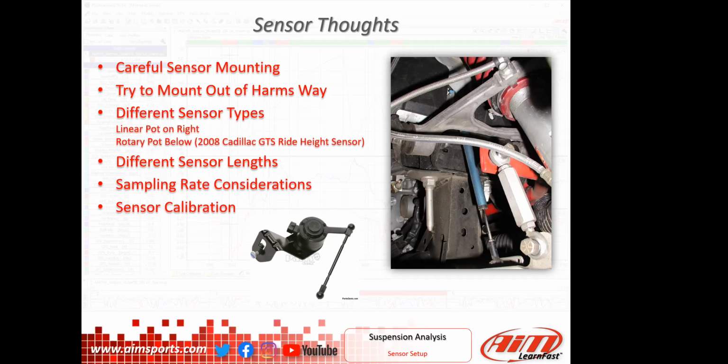These are expensive sensors. They're very powerful tools, but take a little time and think about how you're mounting them. Certainly you're going to end up taking the spring off the car, off the shock itself, or out of the system. Take the torsion bar off, whatever it happens to be, and cycle the thing the full direction. Make sure that this thing is mounted correctly.